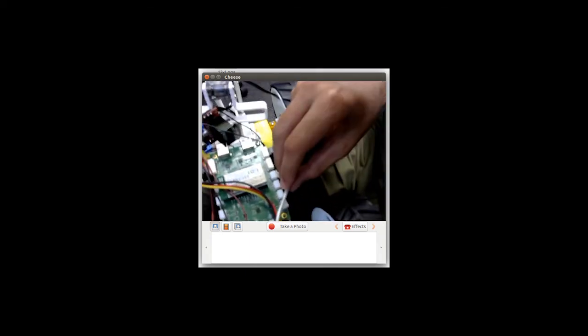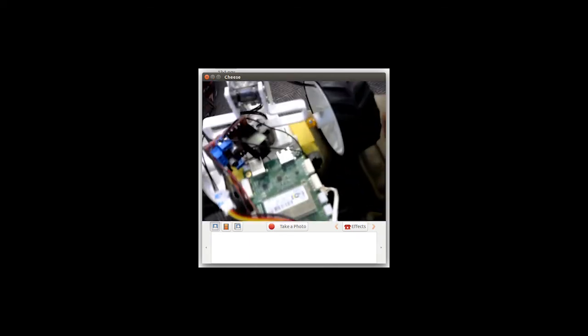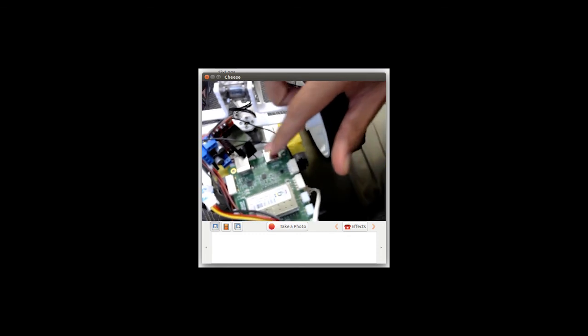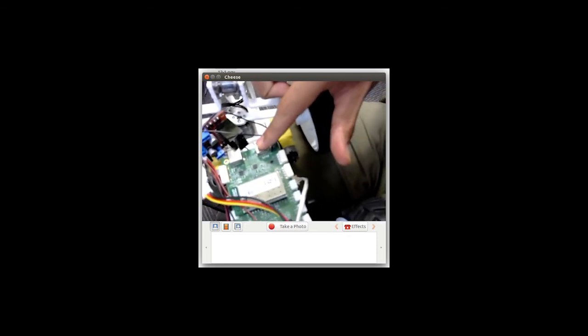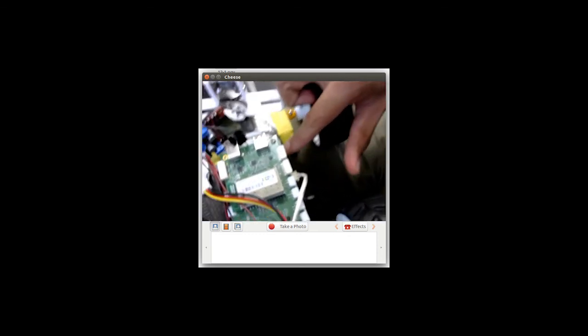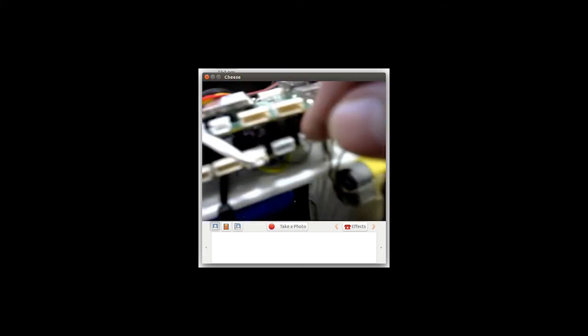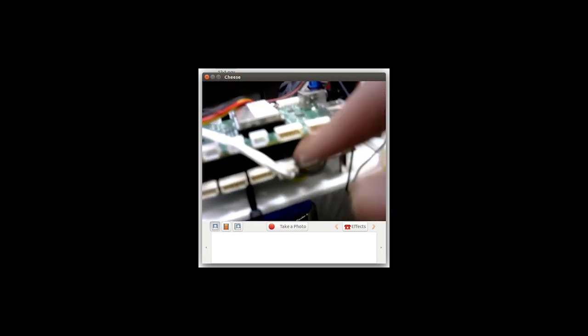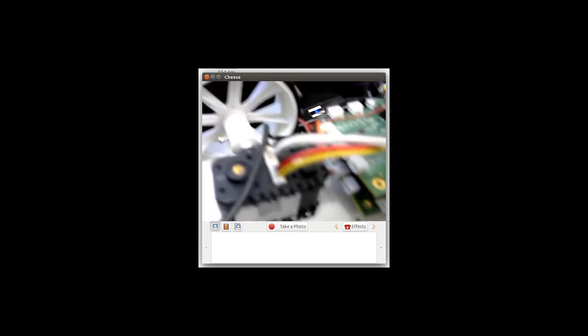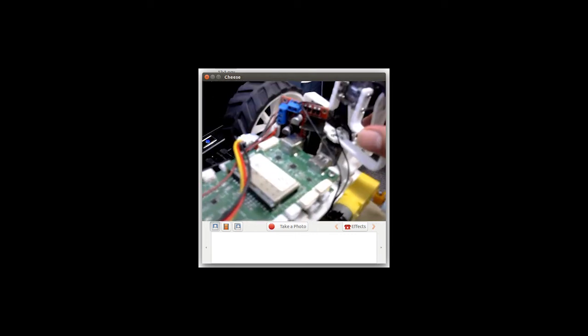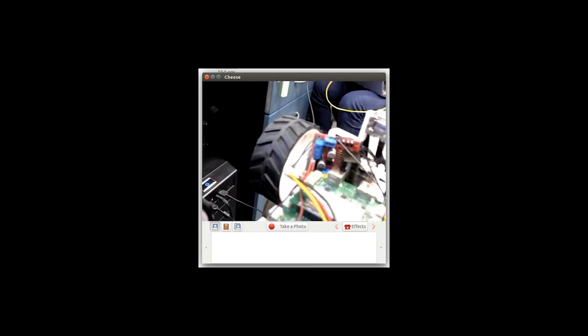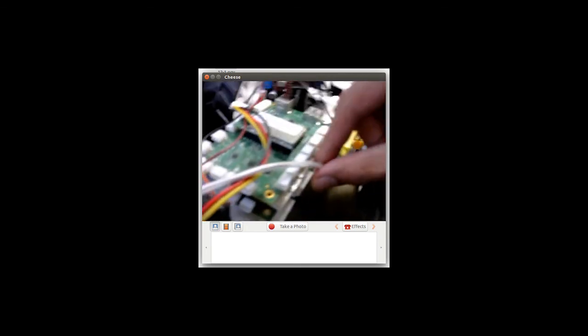So for the wiring of the Dynamixel, it's pretty simple. We have the USB port over here, so looking from that direction, basically it's on the bottom. You will see, we will give the wiring schematic as well. We connect the Dynamixel directly, and from here the other wire is actually going to the other Dynamixels over here, so don't worry about it. So this is the wire to drive the Dynamixels, directly going to this motor.